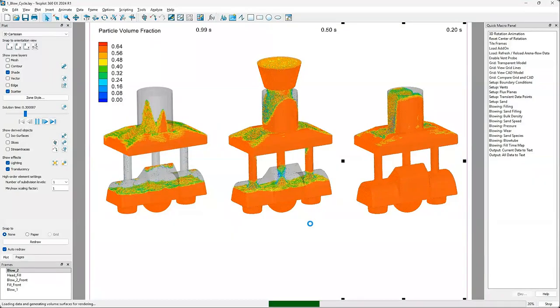So now we've got a full cavity, and we've done that double blow study. In double blow, it can be cycling through a magazine, looking at sand levels, starting out high, just running it down, emptying out the core cavity, refilling it. You can do a lot of useful studies now with this added feature of restarting with a previous sand location. So this is what I had to show.